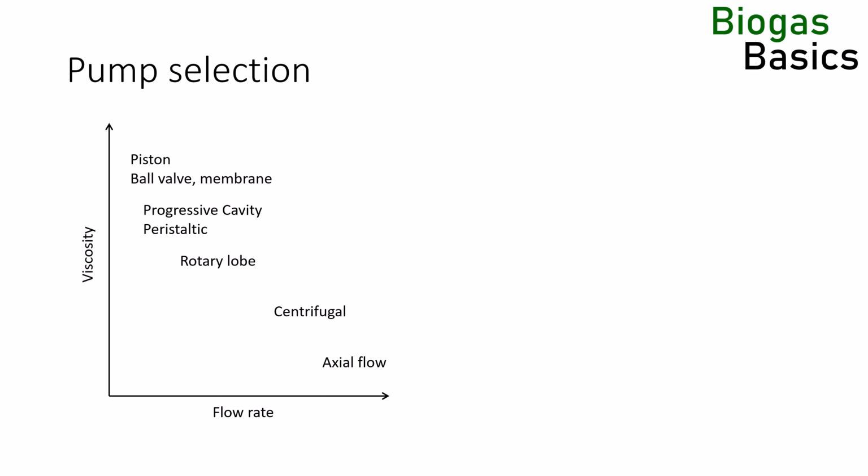Progressive cavity pumps can typically pump up to 100 cubic meters per hour before they become too large to maintain. They offer a good mix of volume flow, ability to work with high viscosity, and wear resistance. Peristaltic pumps have a similar behavior to progressive cavity pumps. Piston pumps are used for low-flow, high-pressure applications around feeding solid rich feedstock suspensions. A later part of this mini-series deals with feeding systems and describes pumps for feedstock, digestate suspension, and dilution requirements.